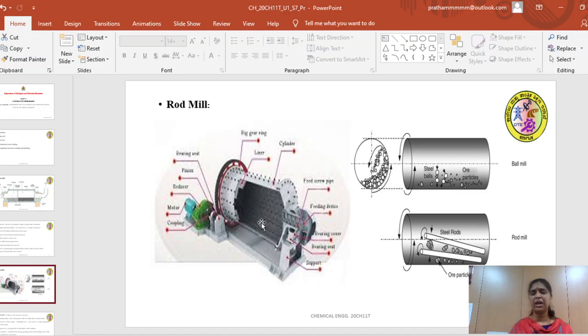When the grinding starts and the mill rotates, as we have observed in the laboratory, the sound is so loud that we cannot sit in the laboratory during the reduction process. We usually run it for about 10 to 15 minutes for 1 kg of feed material, to grind it to a very fine powder that can pass through a 200 mesh size screen. The sound is unbearable.